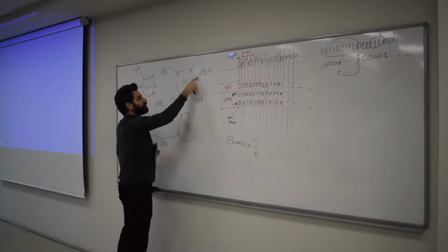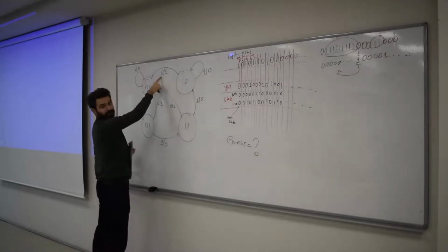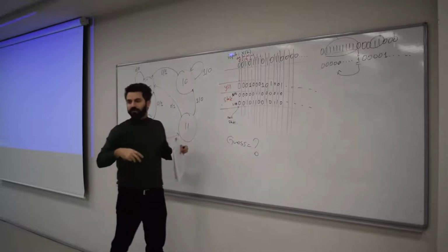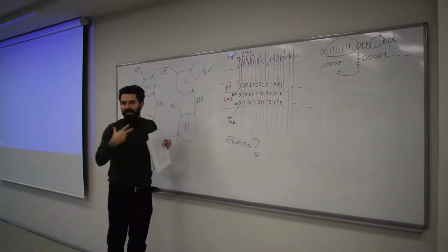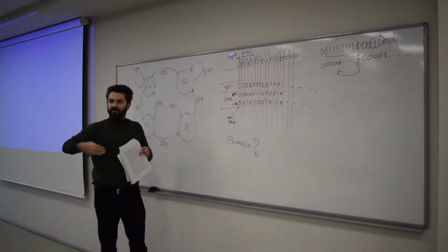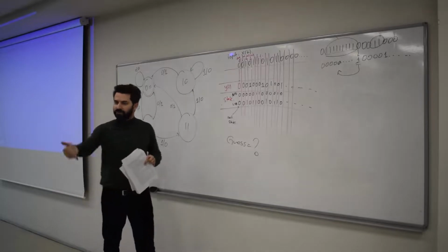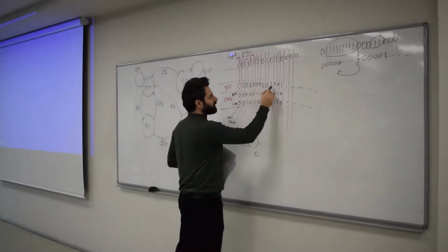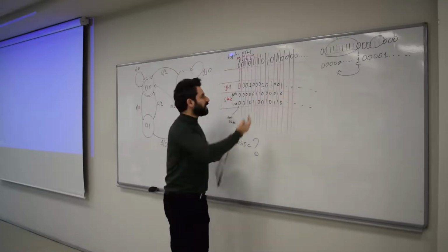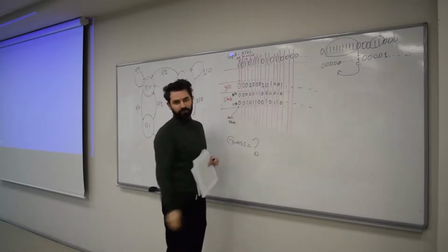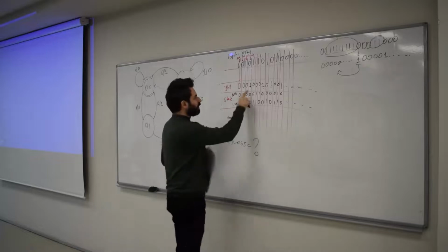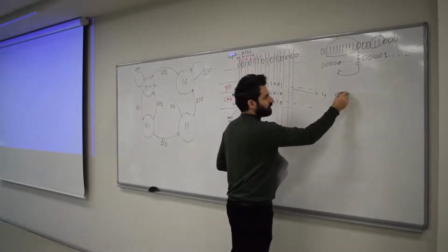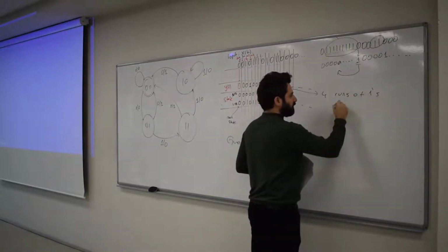And finally, when you see a 0, input 0, you go back to this state, which is actually like absorbing all consecutive ones until you see a 0, and then it pushes out a 1. So what is these ones then? Well, those ones actually tell you how many runs of ones you have in the input. For example, if you sum them, 1, 2, 3, 4, that actually says there are 4 runs of ones in the input.